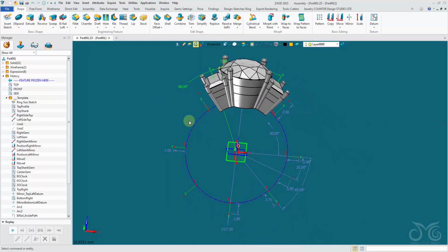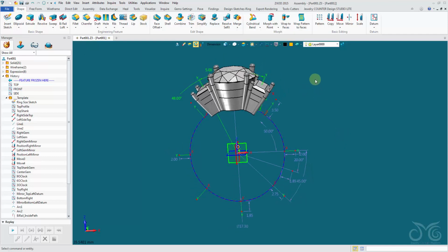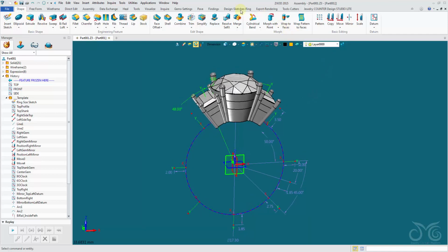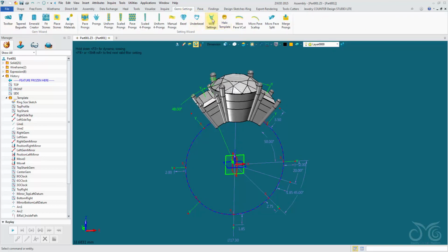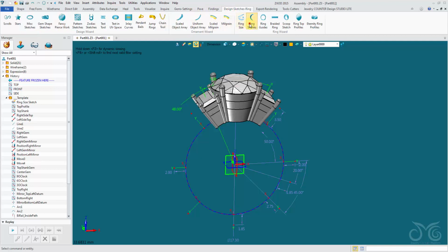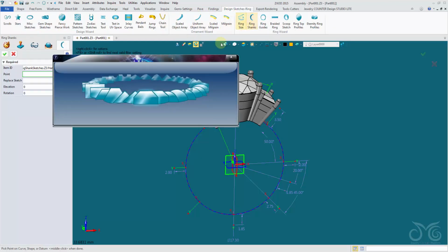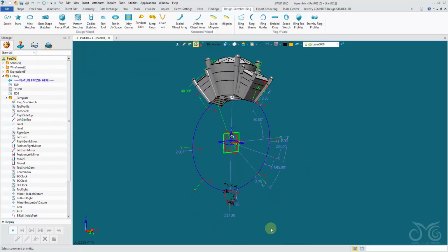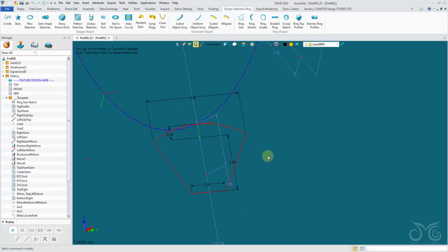So you can see how we're building up our ring pretty easily using our template. And the template also gives us control over the placement of our stones. That is one of the reasons they're so useful. Next up, let's quickly drop in a ring shank to finish this off. Any will do. Just put it in at the bottom here. These seem like decent enough dimensions.